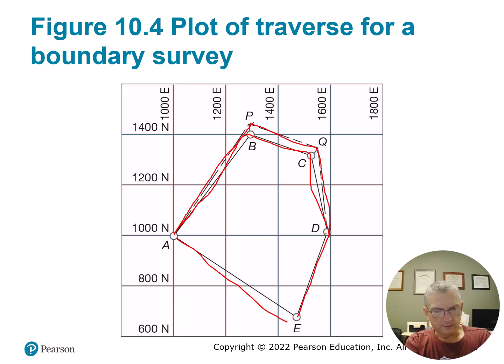So the authors of the book seem to think that open traverses are fine, but even in route surveys, you're not just going to run an open, unadjusted traverse out there. They did decades ago, and sometimes we find where they had errors in their original route survey because you can tell that the bearings on the roads don't match in a place or two. So be careful. Don't worry about that section of the book very much there.